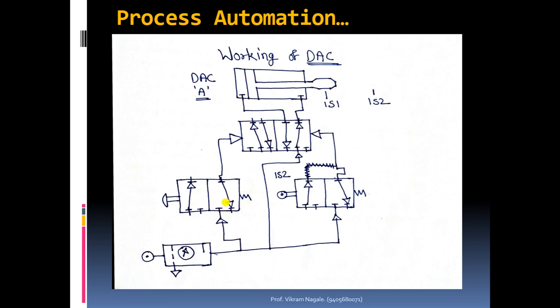Okay, and before activating this valve, this right side block should be in active connection with this cylinder, and there should not be pressure on the right hand side of the valve. Okay, and because of this, what will happen, we can apply pressure on the left hand side of the valve, and that will give us extension of the cylinder.